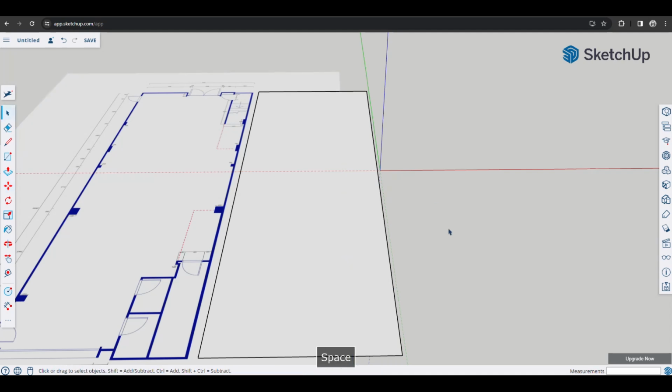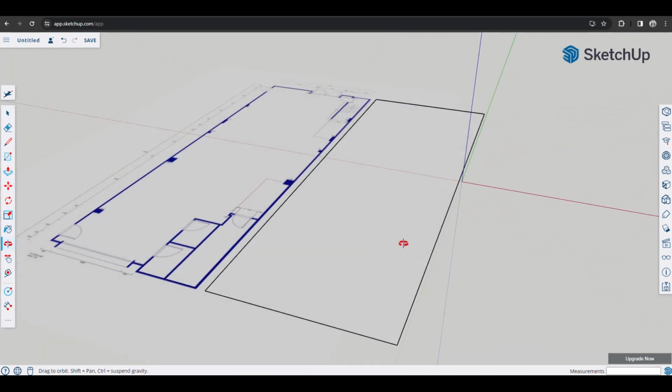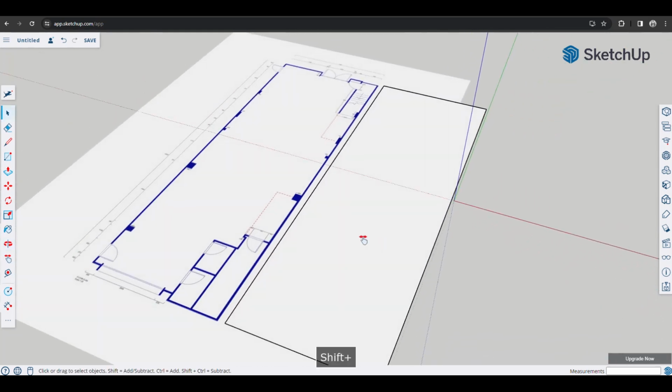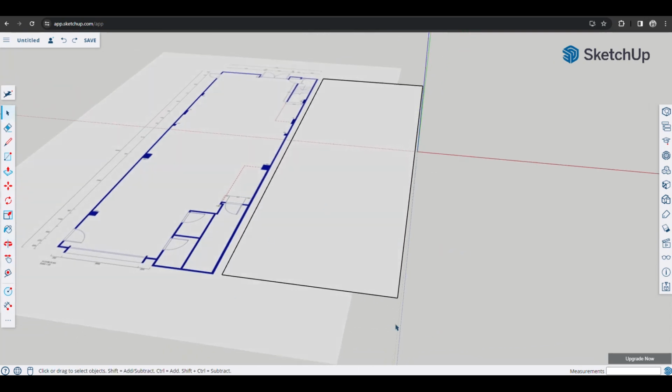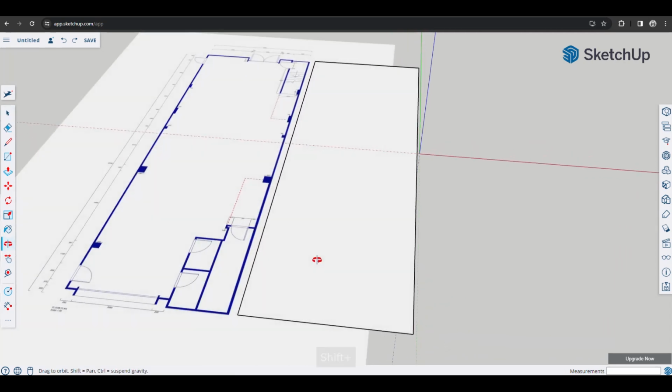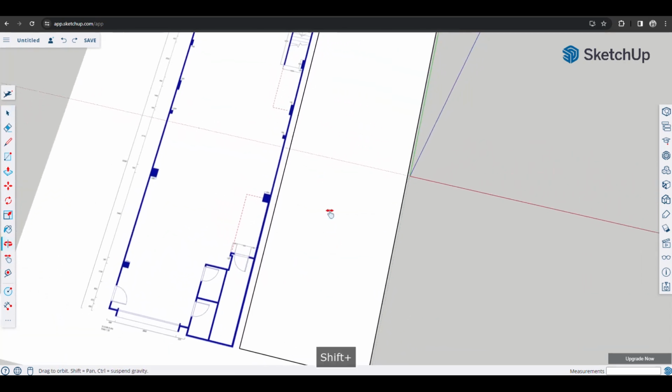Okay, so this is the floor that we work on, right? So how SketchUp works is that you click the function, and then you actually have that function going on. But once you finish it, you can just click spacebar, and it goes back to the select function. All right. So that's why I've been pressing spacebar. If you see at the screen, multiple times I'm pressing spacebar. Okay.